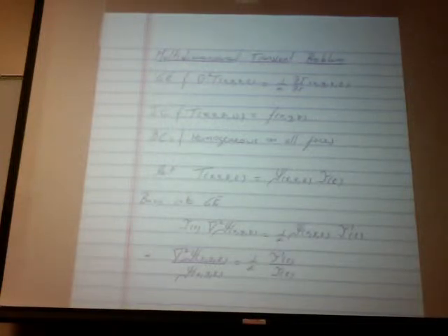And again, the governing equation shows a function of space on the left and a function of time on the right. The only way that they can be equal to each other is by both being a constant, and we're going to pick that constant to be negative for the same reasons that we've been saying. So in the t direction, we have tau prime of t plus alpha lambda squared tau of t equals 0, leading to tau of t equals a times e to the minus alpha lambda squared t. That is the solution of that equation.